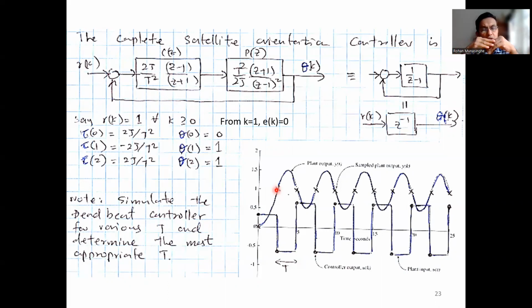Now error is 0 based on the deadbeat, and you get minus 4 times something, and you set that torque and execute it, and you go to sleep. So because of this negative torque, now this acceleration, which the satellite has already acquired, now it slows down, right? And then it comes to 0 angular speed, and then starts moving the other way.